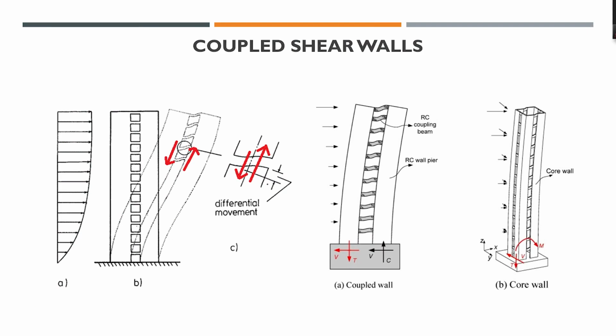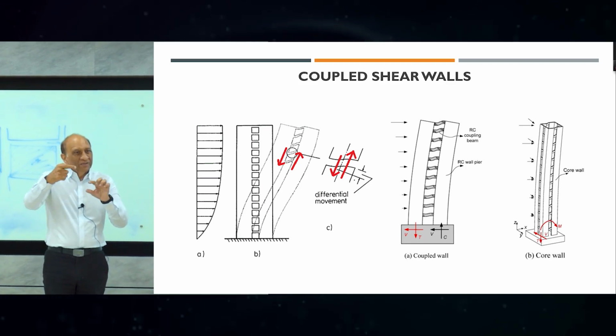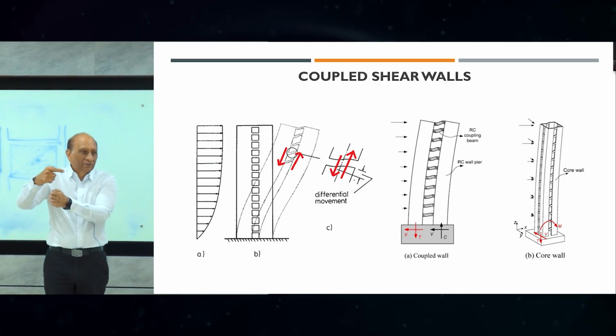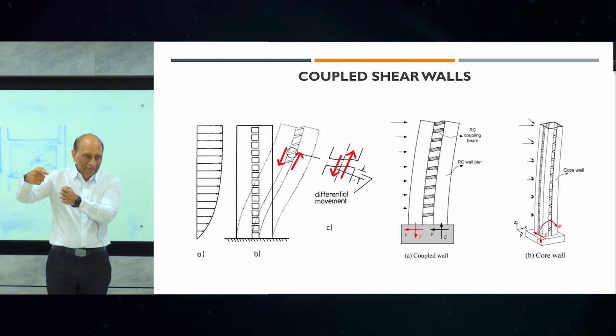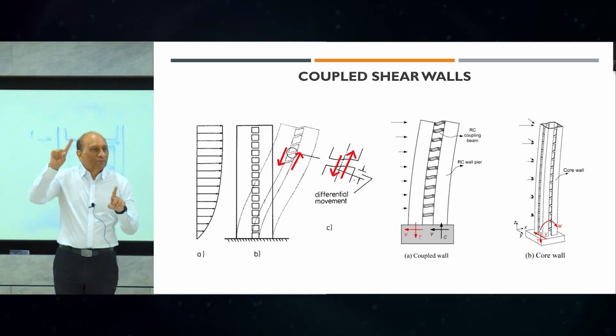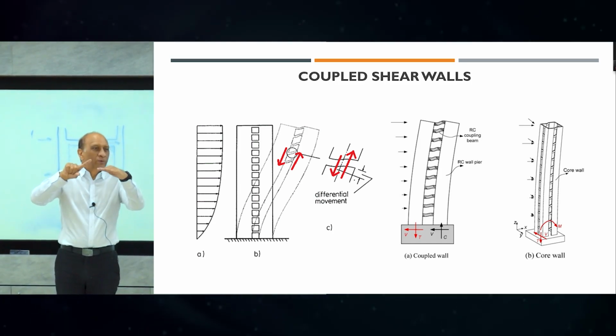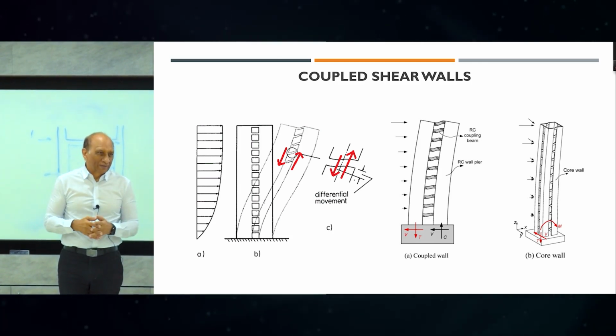We do not calculate the reinforcement from the moment coming from the design, but we calculate based on the maximum shear that can be produced. So we reverse calculate based on capacity design procedure, right? So we first of all calculate how much shear it can take and what will be the moment corresponding to that. And then we put the reinforcement not beyond that. So then it will yield after that moment.